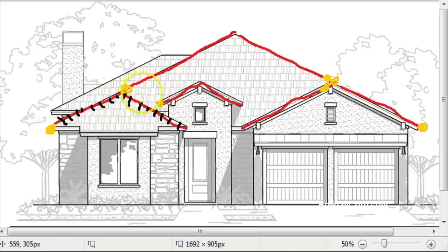We have to have a decentralized system because there are power limits within the cables or the strip. And so we have to put these controllers all over the house. So let's say, for example, we had a pixel-based controller that was a large 16 output unit. We have it right here. If we had it right here, getting the cable all the way over to here and all the way over to here would be well beyond a typical range of about 10 feet.